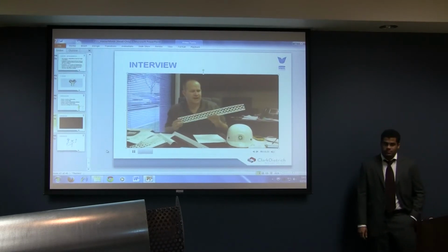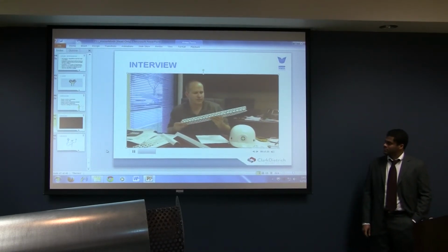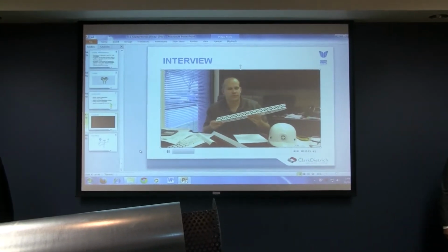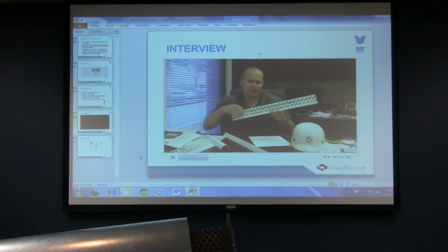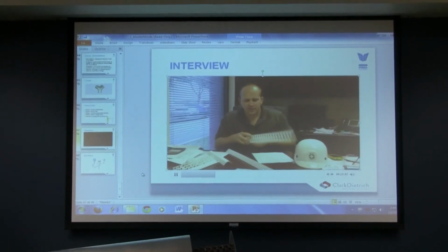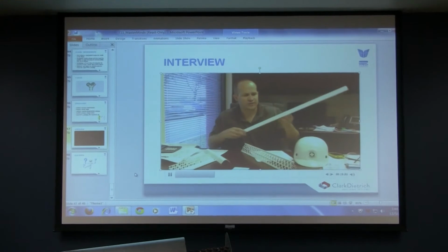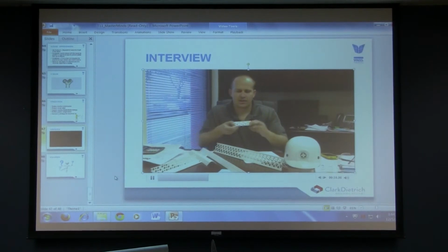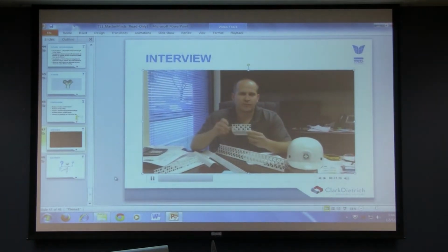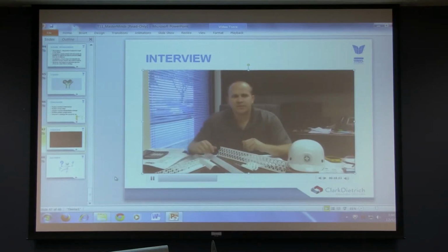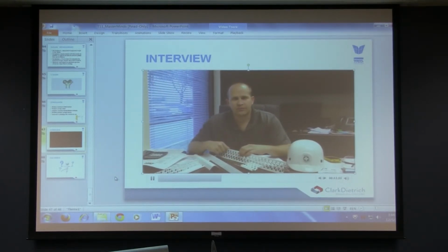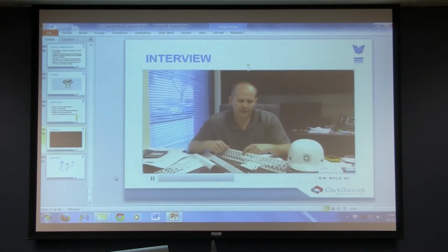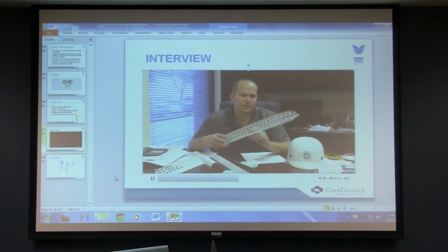Thanks, Eric. What happens after the extrusion is it goes through a water bath and a puller, and then into a secondary process where we punch holes in the member. These holes we call punch outs are a problem that we have today. You'll see a variety of shapes: our drywall products are very small and our stucco products are very large. All these punch outs have to be diverted back into the product. Currently, they're collected through an air-driven system into gaylords and then recycled into new parts. Our process is not efficient because the air constantly flows at full pressure, and the parts often end up on the ground because of an inadequate collection system.